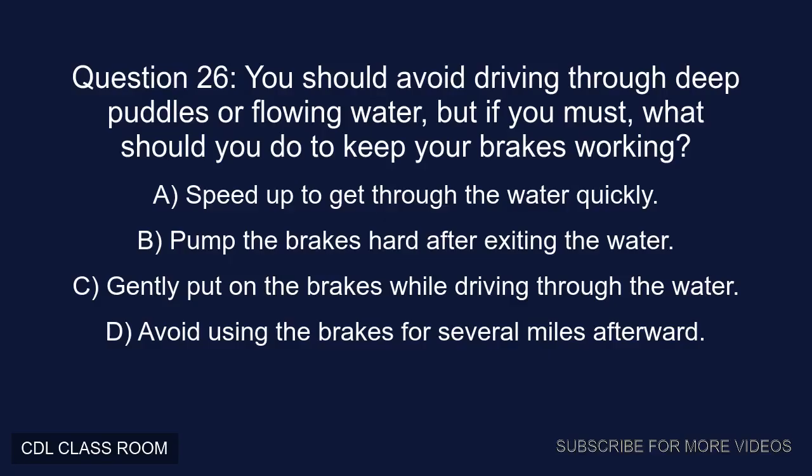Question 26. You should avoid driving through deep puddles or flowing water, but if you must, what should you do to keep your brakes working? A. Speed up to get through the water quickly. B. Pump the brakes hard after exiting the water. C. Gently put on the brakes while driving through the water. D. Avoid using the brakes for several miles afterward. Correct answer, C. Gently put on the brakes while driving through the water.